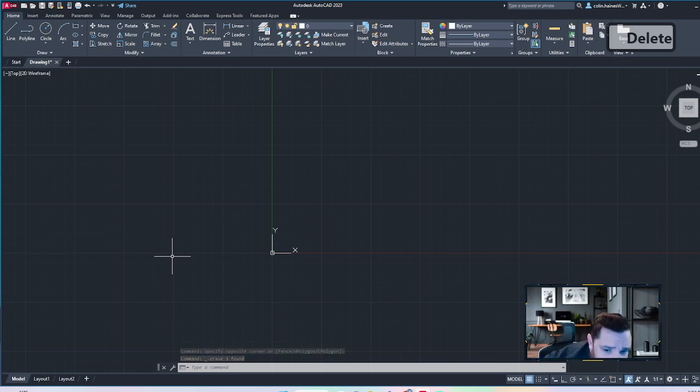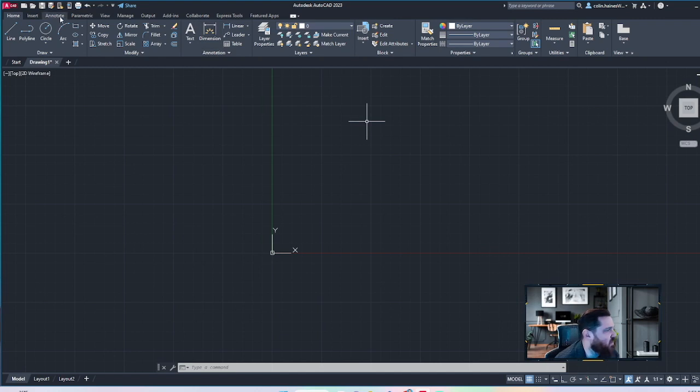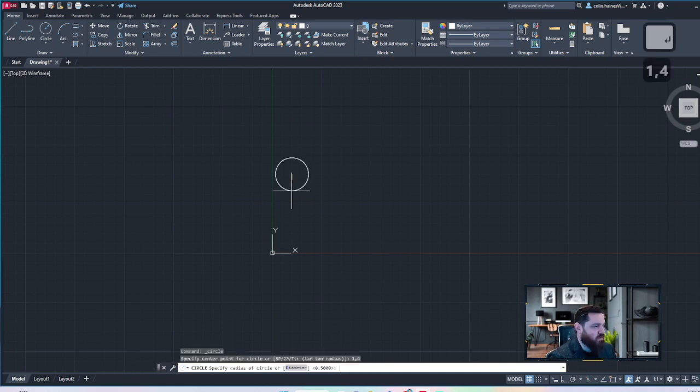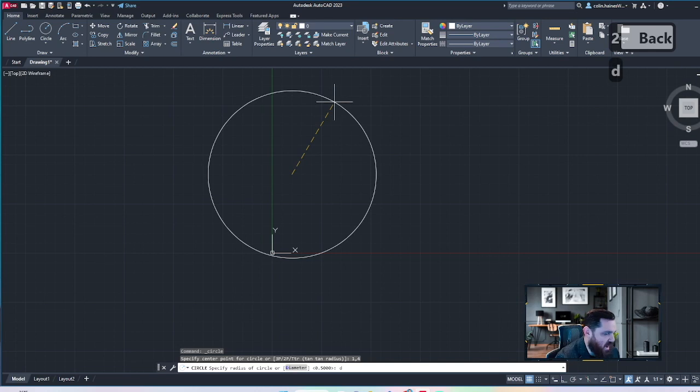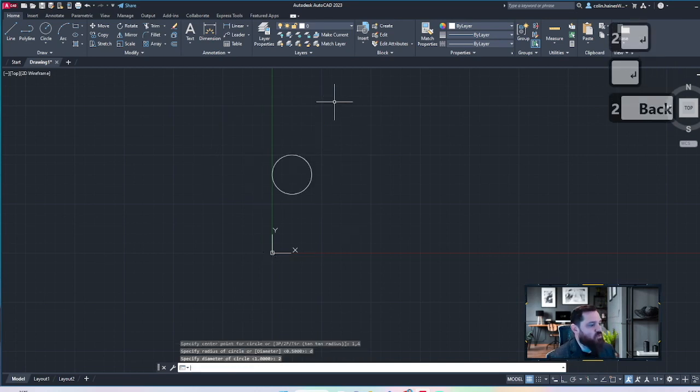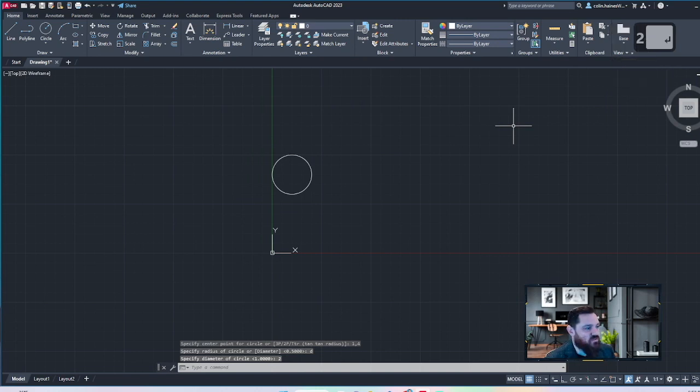And to close out this video, let's take on our first drawing together. Let's do something nice and fun. I'm just kind of shooting from the hip here. I already grabbed the circle. Let's go 1,4 with our circle. And I want a diameter, so I'm going to type in D, enter, sorry. And I want a diameter of 2. So I've got my first little circle there.